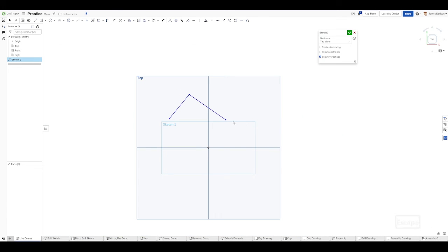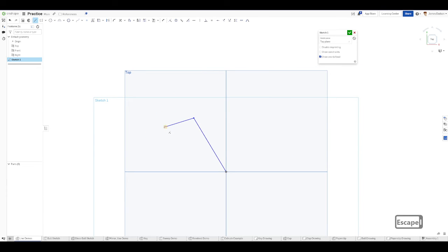You can also make something coincident to the origin. Press I. Now it's coincident to the origin and to this point. And this is super useful for creating all types of shapes. I can make this coincident to that, make this coincident to that, make it a right angle, all sorts of different things. And it's another one of those things that gets auto-suggested a lot. So, yeah.